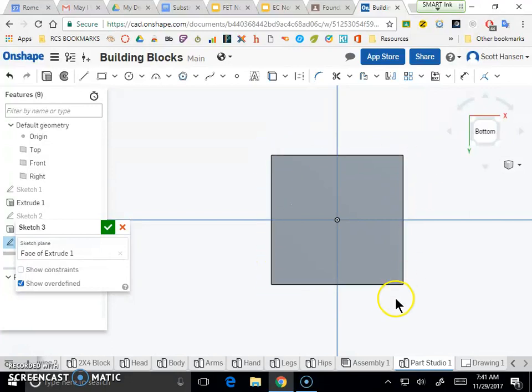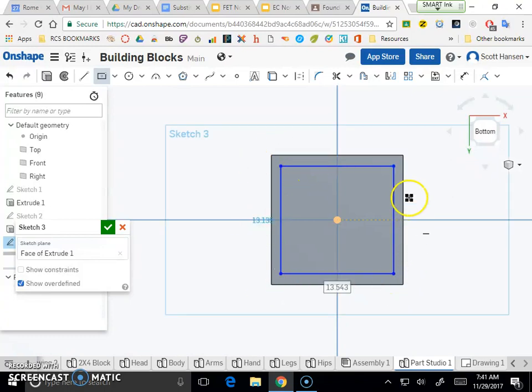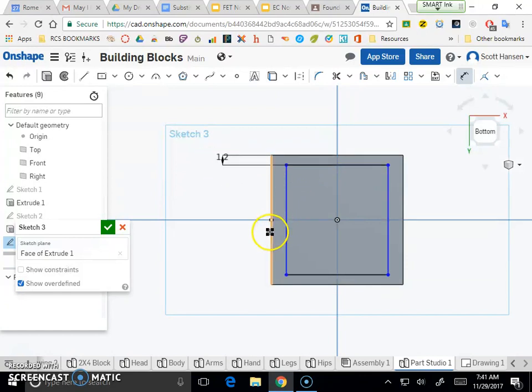So we've got the outside edge, and we've talked about this before. That edge has a thickness to it. So to create that thickness, I want to create a center point rectangle that's a little bit smaller than this block. And so once I've got that, you should have some dimensions that have measured the thickness of those edges. You'll have to specify those dimensions on 2 different sides to fully define this. So that adds a thickness to the Lego block.